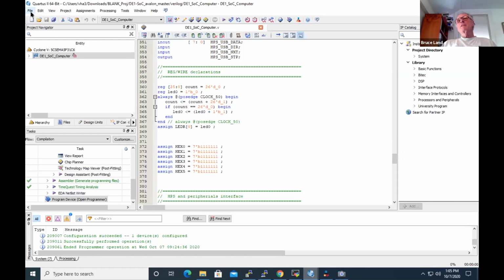The interesting thing about these phase lock loops is they will do fractional frequency multiply. Any rational fraction with no more than 6-bit accuracy in the numerator and denominator can be synthesized. If you want more information than that, we'll have to draw it. It's a control loop.